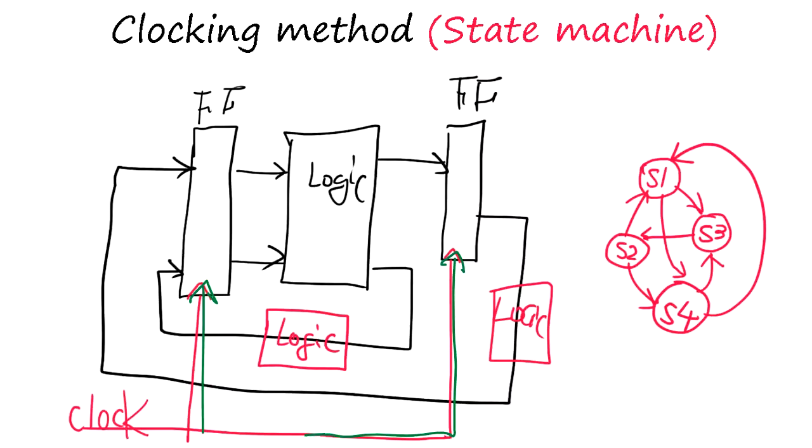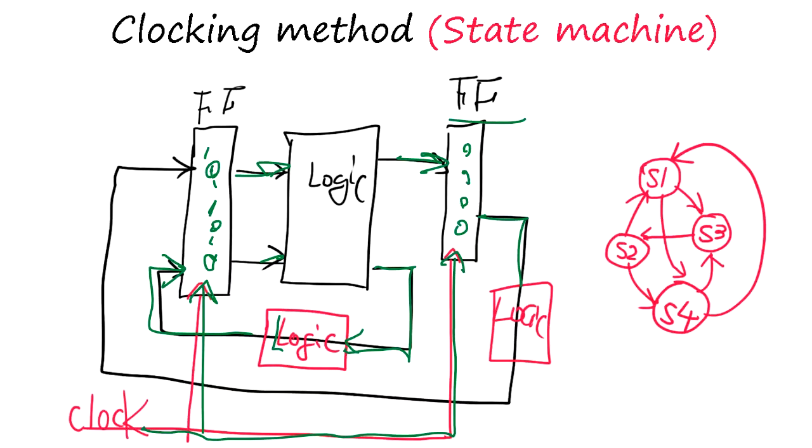From register to register. A register is a collection of flip-flops, and you have a state 0101 and go through the logic, and sometimes go to a different flip-flop and are stored partially. Some of them go through the logic array and go back. Some of them go all the way to the second stage or third stage and go back.